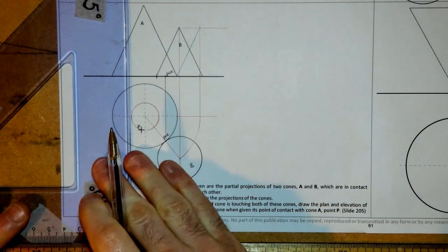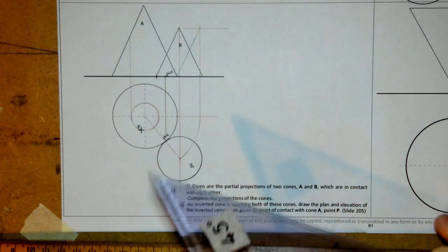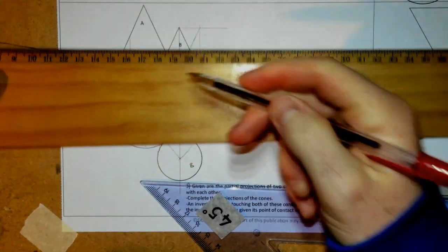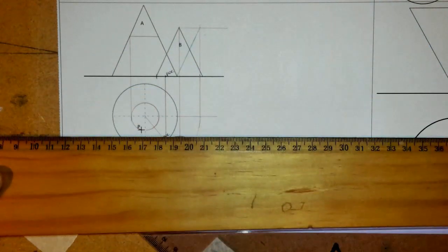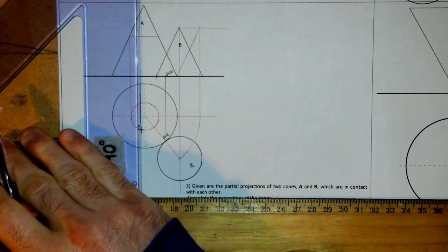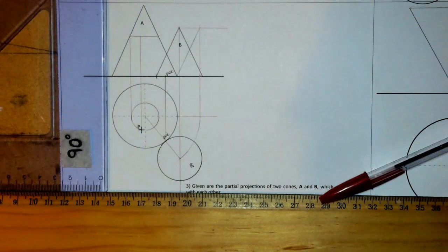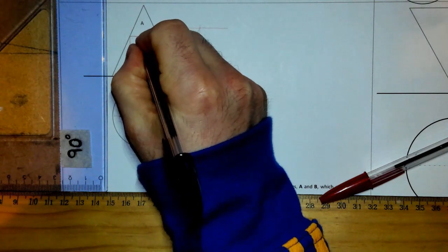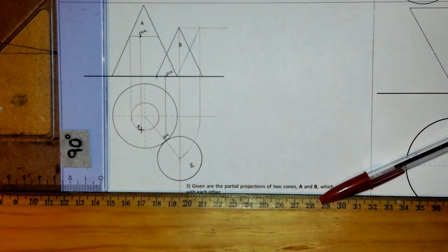When it hits the extreme generator, project that up, and basically it hits the extreme generator here. That there is what my cut looks like, but if I want to find the exact position of point P, I project point P up there, and I've now found P in my elevation, which I'm actually going to call POC, okay, because that's the point of contact.